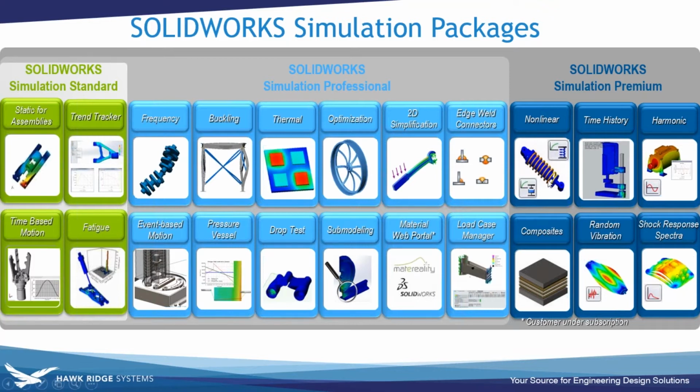And moving up the ladder, we can do the exact same thing within Simulation Premium with the nonlinear study. Right? I'll talk about the difference between linear static and nonlinear, but with the nonlinear study, we still get results of stress and displacement, where we can also input directly a temperature load on a specific face or a component within your assembly, or we can also transfer in those thermal results from SimPro or even Flow Simulation. But because we're dealing with nonlinear, which is a function of being able to incrementally see how stresses are developed through the different time steps, we can link a transient thermal analysis to a nonlinear one. It will make a little more sense once we get to that point. But just letting you know, from our simulation packages, there are a lot of different options to incorporate a thermal result into a structural analysis.